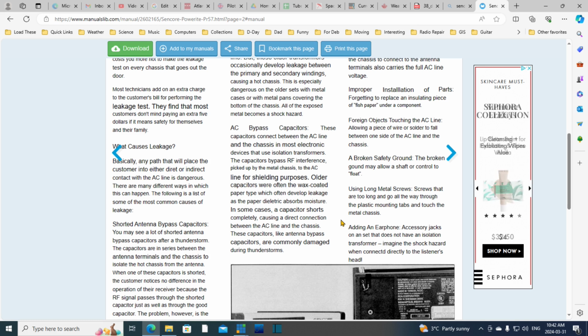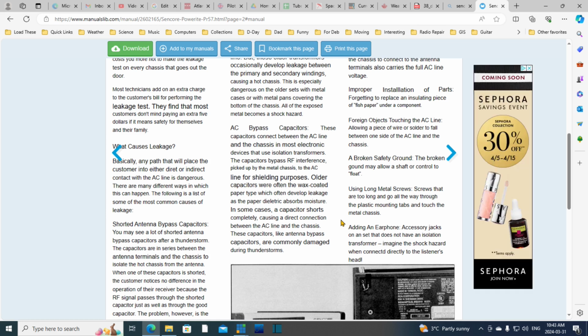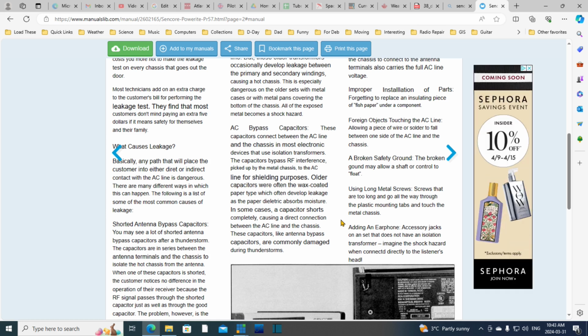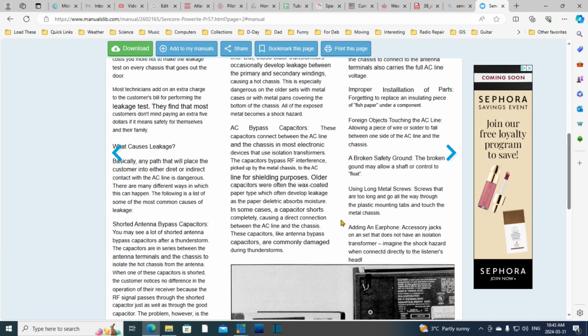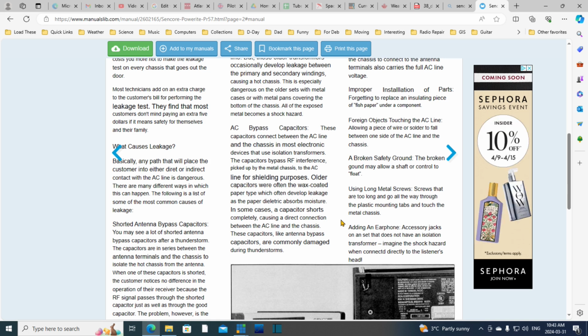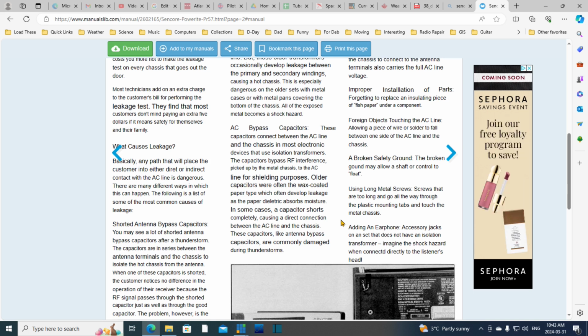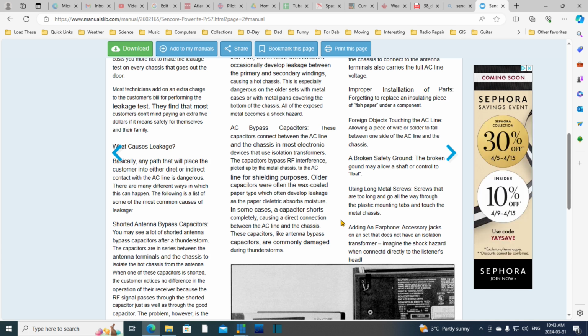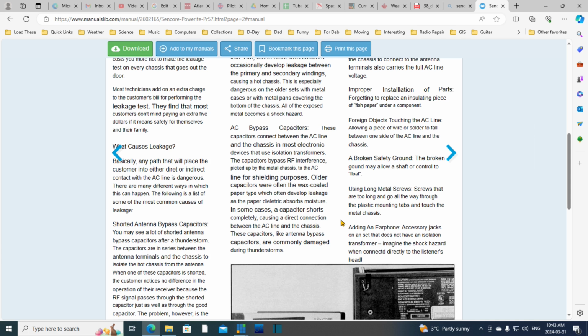And the reason for this is to make sure there's no voltage difference between the tower and the fence, because guys go inside there to work and they don't want to touch a fence that's grounded and touch a tower that's at a different voltage and get a shock off it. And you're talking, hydro tower, you know what kind of shocks you get? Deadly shocks for sure. So all this stuff is tied together. It's called bonding. So the fence and the tower are the same voltage all the time. So there's no voltage difference, can't get a shock. That's called touch potential.